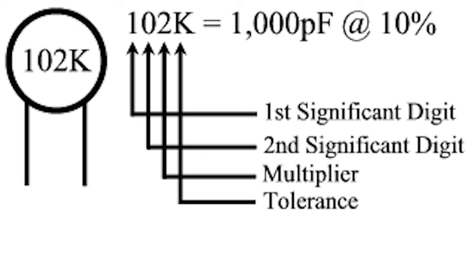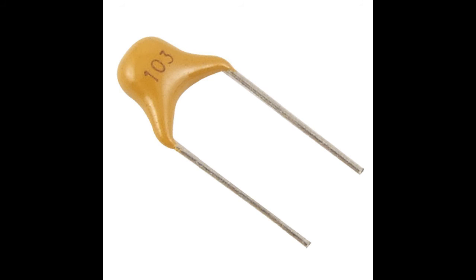Ceramic disc capacitors have markings that are a little trickier, but they work similar to the resistor color codes. It's assumed that the resulting number you get from doing the math here will be in picofarads. So this ceramic disc capacitor is a 10,000 picofarad capacitor.